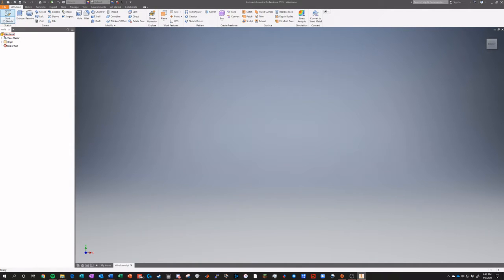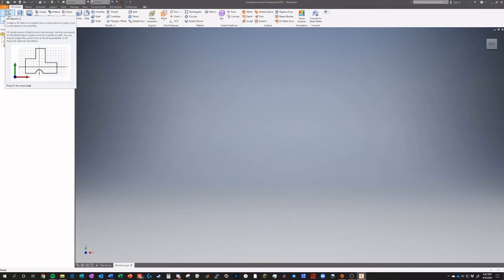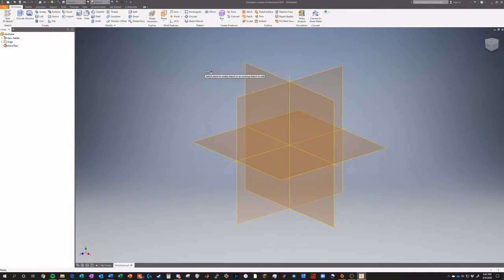All right, so I'm not going to be recreating an entire FSA frame in this tutorial, but I'll just show you a couple of the general things. So, wireframe is exactly what it sounds like. You're pretty much going to leave everything as a line. You don't necessarily want to make them into solids because you'll be dragging those solids along it. Pretty similar to how a sweep works, but it kind of is already automated. We'll get to that in the next one, but essentially right now you basically just want to set up all your paths that your tube profiles will be swept along.